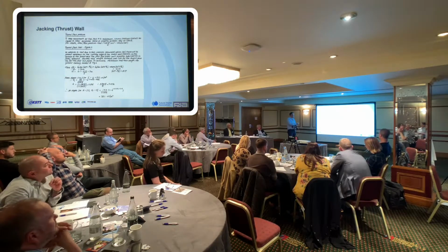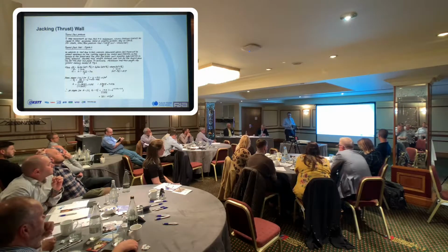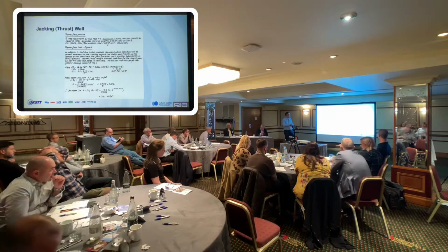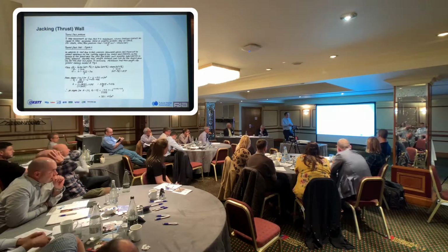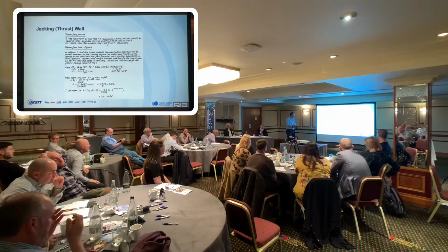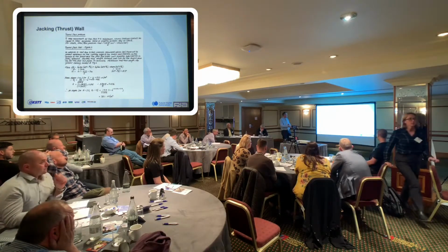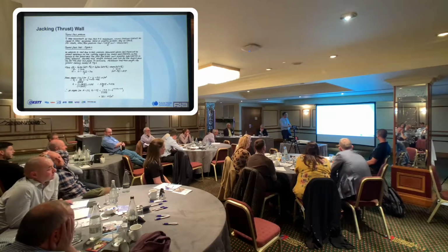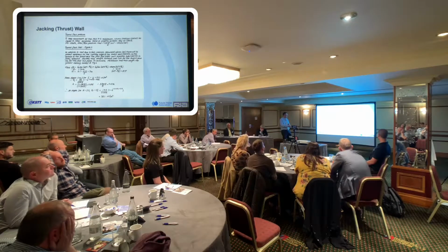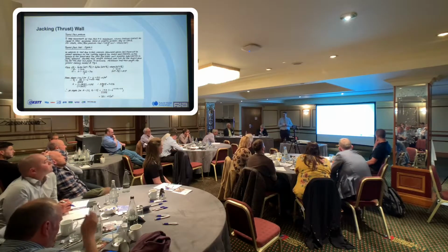So face pressure, and this relates to that slurry pressure that I was talking about in the front of the machine. And then there's the face load. Again, it gives you a little bit of a description. It talks about the face load, and I think I said it should say somewhere, yeah, about resistance on the cutting edge and on the shield and a bit of friction. But it gives you the simple calculation, so at least it's a starter for 10.